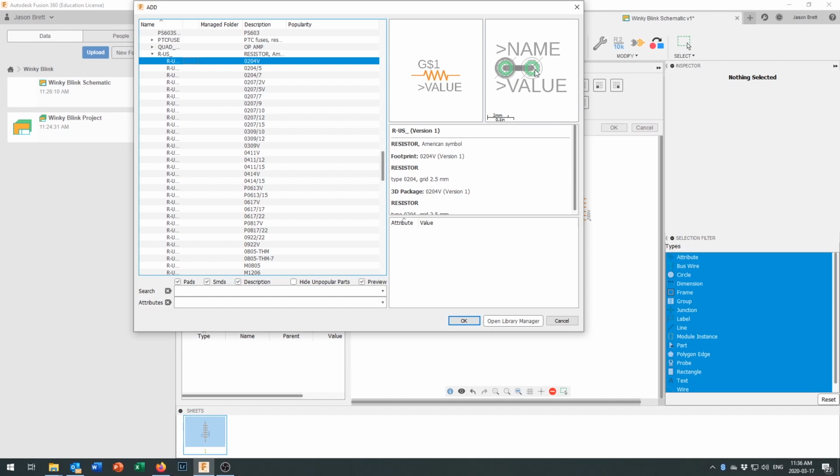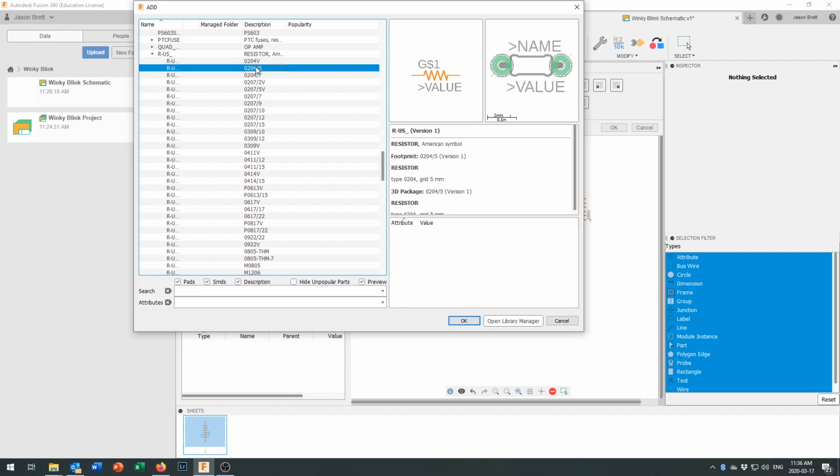And that's a good way to install a standard 1/4 watt resistor like we'd use in the shop, and it uses very little space to do it. Only thing is it makes it a little tall, maybe easier to be bumped or damaged, so we probably won't use that one. And you can see that the reference right on there has a V for vertical. Here's something. So we've got a resistor right here, and the symbol looks like a resistor value. Footprint, that's what our resistors look like when we put them on a board.